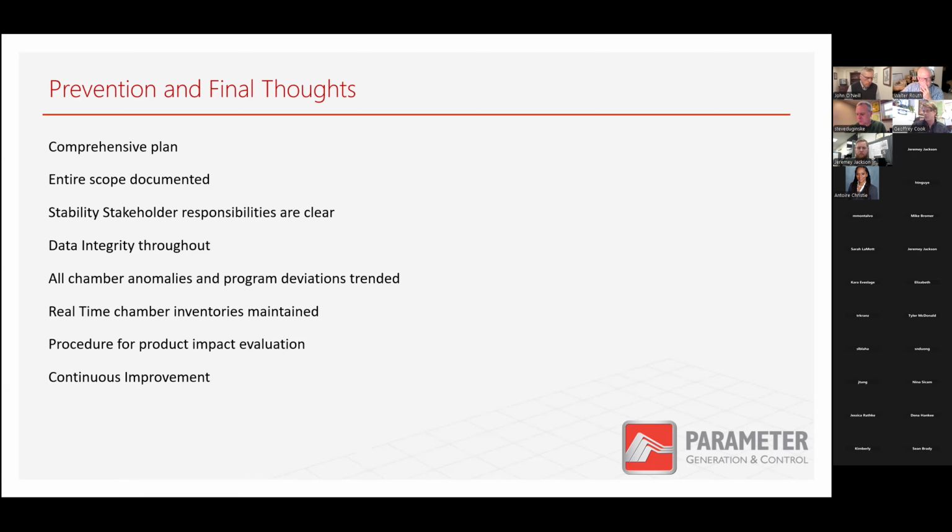Going back to the alarms comment and question, it's very important to consider your alarm trip limits and the timers that you place on those alarms. You might want a 40/75 condition to be more closely monitored and alarm you sooner. You may end up with some nuisance alarms based on door openings and things like that, but that may pay off in the long run just to be notified a little sooner.